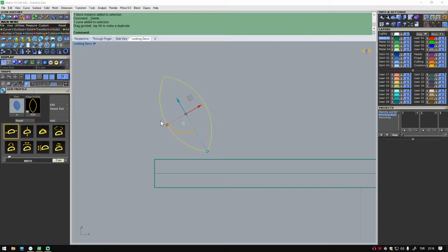If you don't want this orientation, if you want it oriented right side instead of your left, you can always go back with Command Z, and after clicking, instead of typing 30, you can type -30, which stands for -30 degrees. And if you want to resize this for smaller, you can use this little square there and this one over here.